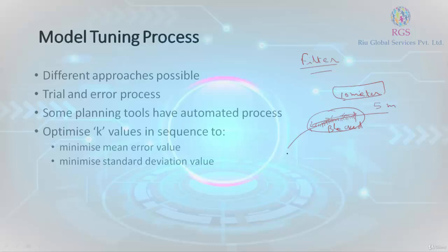It is ideally the size of your map data. So if your map data is 5 meters, you need to consider this 5 meters. So that in 5 meters, if I have 10 samples, I will consider only one average or one filtered sample from those 10 values. And then for the next 10 meters, I'll consider only one value. So in this case, your CW file will become smaller and it will become easier for the tool to calibrate the values in a better manner, right? So this is the filtering of distance.